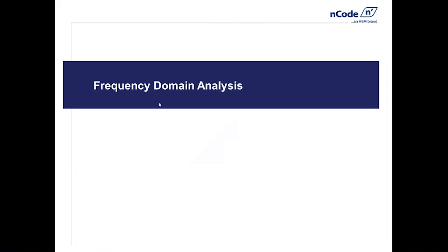Now we can have a look at frequency domain analysis. Here we're interested rather in the frequency content, typically because we've got modes, modal behavior of a structure or a component, and we want to know whether we are close or not to these modes, for instance. And typically we also want to look at the distribution of amplitudes over the frequency range, and whether it is low frequency, broadband, etc.